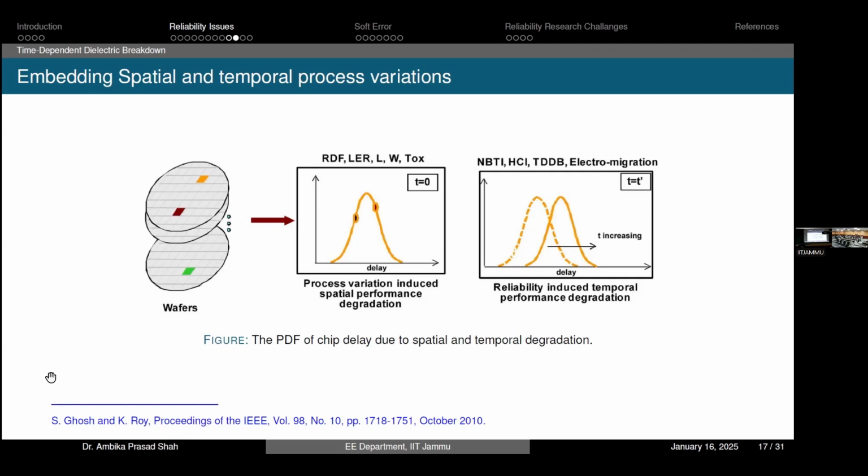So they have to give some guard banding that is required. If they have given some guard band, definitely even after 5 years, your system is going to work. But before that, it is perfectly fine. So that guard banding is required. You should not expect your behavior to be like yellow. It should be like the blue one. The blue one is expected, so that even after variation, you will have some range that can be adjusted later on.